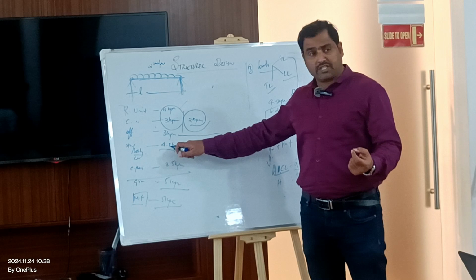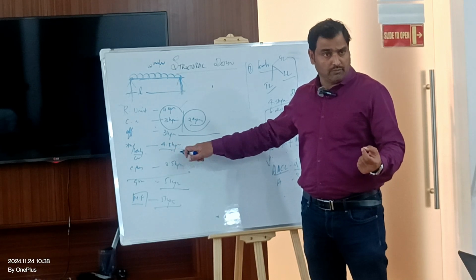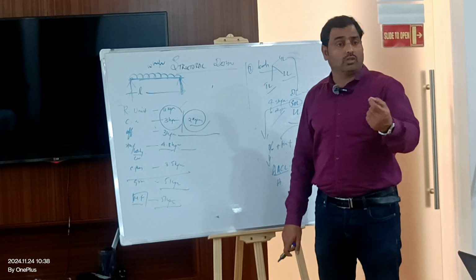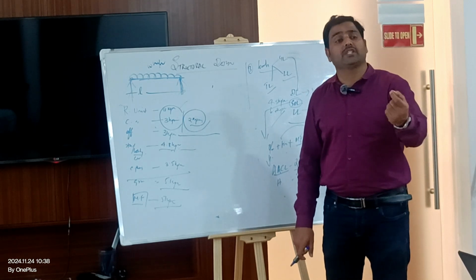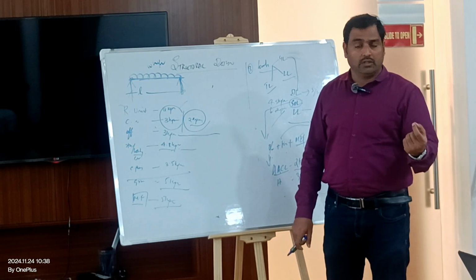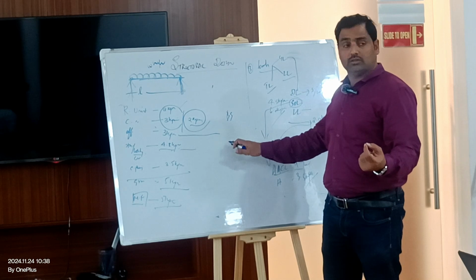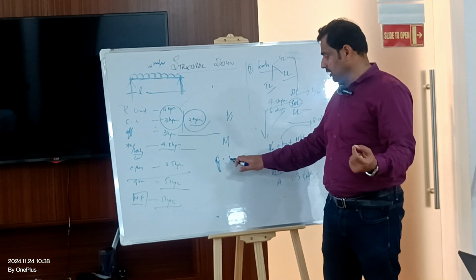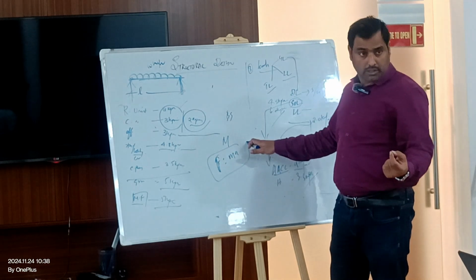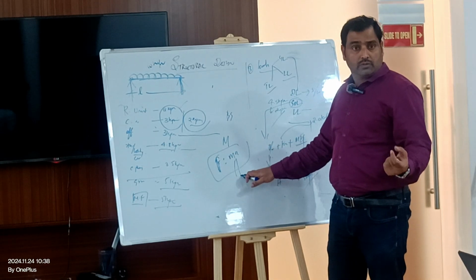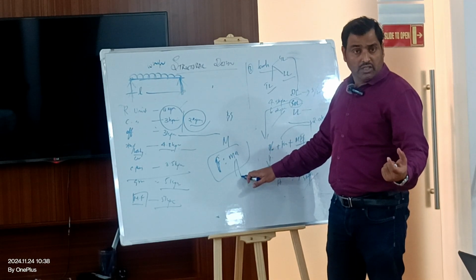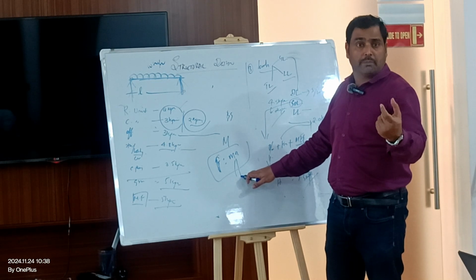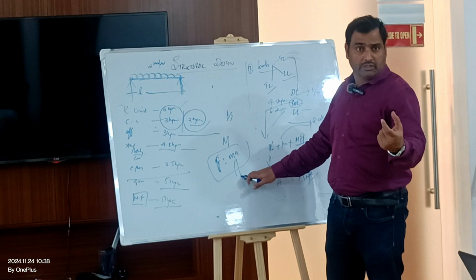If it is 5 or more than 5, you need to increase the base shear in the combination of the load with the live load. You need to increase the percentage. When you are talking about the base shear, which is mass times acceleration, the shear force F equals MA, right? The mass is what? Your dead weight of the structure including your live load. The code is giving the privilege.